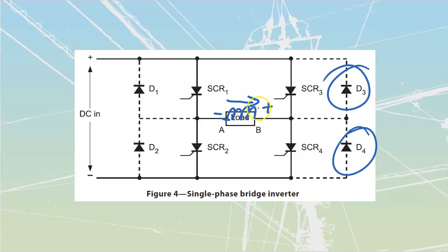Then what we would see is that when we remove that, this would try to maintain its inductor. It's going to collapse its field lines of flux in and around itself. It's going to try to maintain current flow, but it does so by creating its own positive and its own negative. And when it creates its own positive and negative, it's going to need a place that it can go and drive that positive back out.